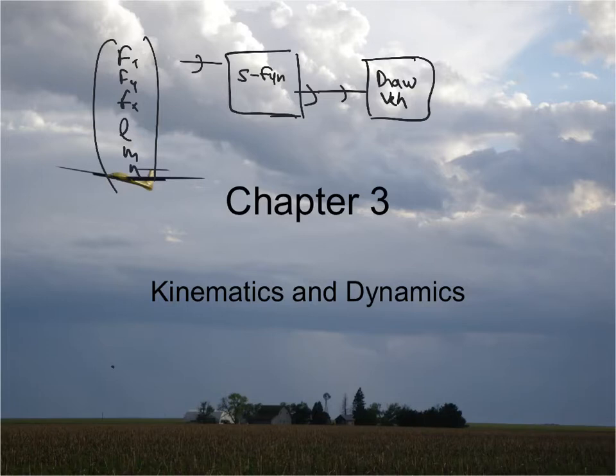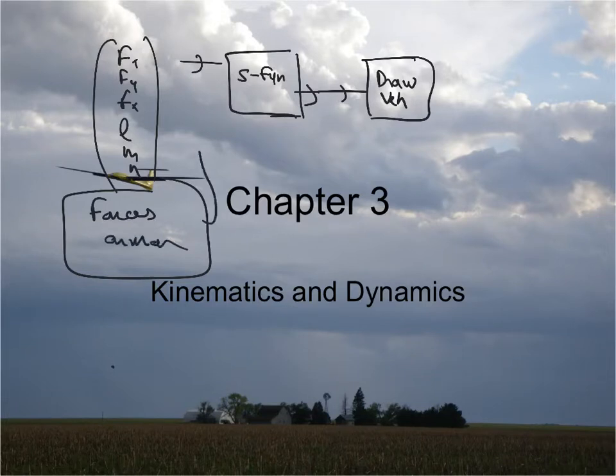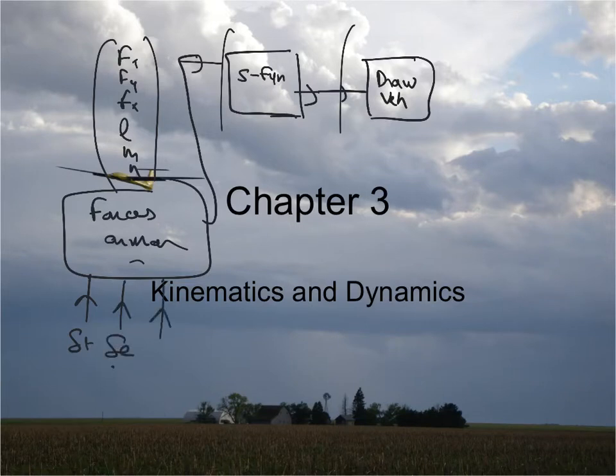How these inputs are used to compute all the states, that's the S function. So next week, we'll be making a block which just computes forces and moments, and then it will replace that input. If you don't do this assignment, the next will not be done, so it's all a systematic way. This block will take throttle, delta T, elevator, rudder, and aileron. So 4 inputs, each from 0 to 1, will go there and compute forces and moments, and those forces and moments will go to your S function here. That's the strategy we have going forward.